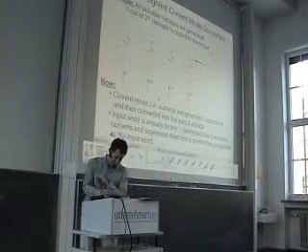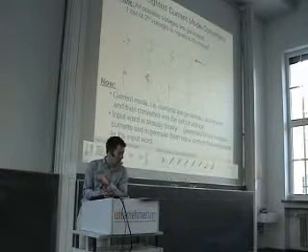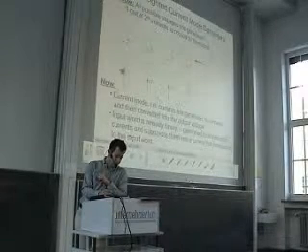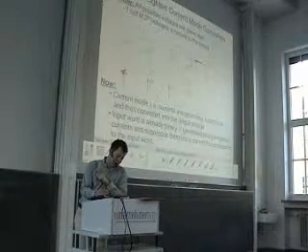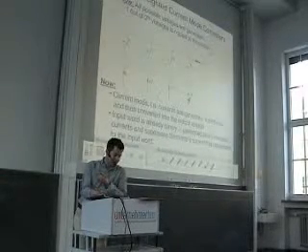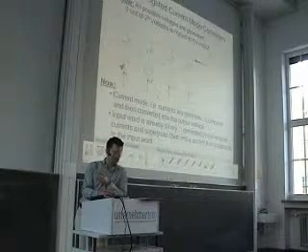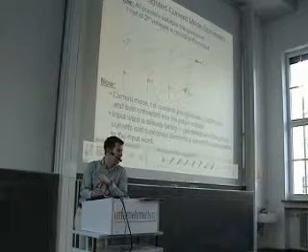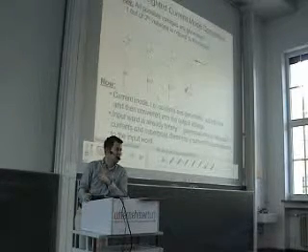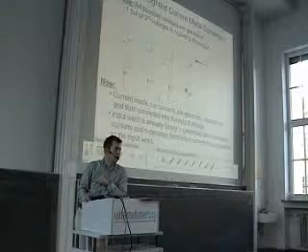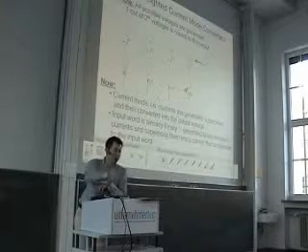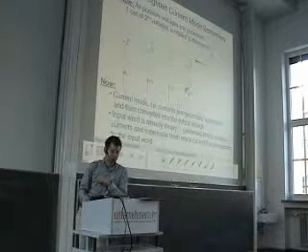You can see here we have several current sources. And these current sources are binary scaled. So we have here a current I, then we have I over 2, I over 4, I over 8. So we could directly say this one corresponds to the most significant bit, this one corresponds to the least significant bit. And by going from one current source to the next current source, the current is always scaled by a factor of 2. And this is the same factor of 2 that we would see if we go from one bit to the next bit.